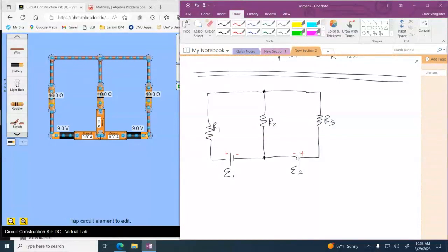So that means under that viewpoint, current would be flowing out of the batteries this way, which is exactly what I see on screen. So when you get to your test next week, you can obviously do the same thing I'm doing right now. Know in advance what the current flows are, and your assumption will be that. Your equations are going to give you conventional current flow answers, which is the opposite direction.